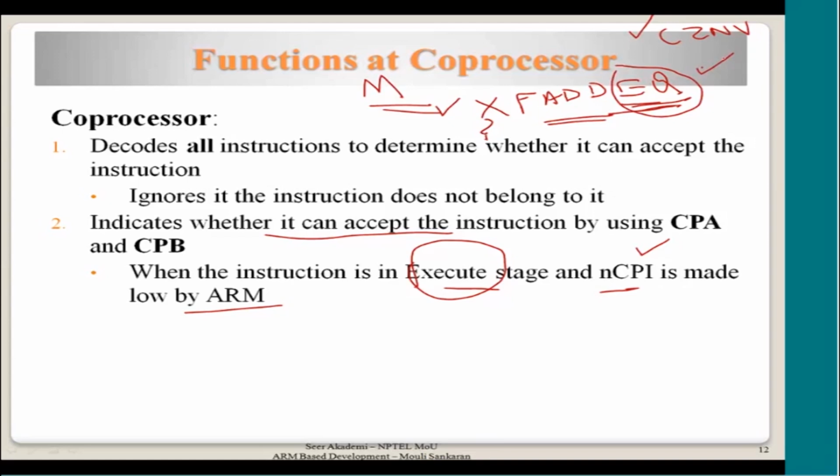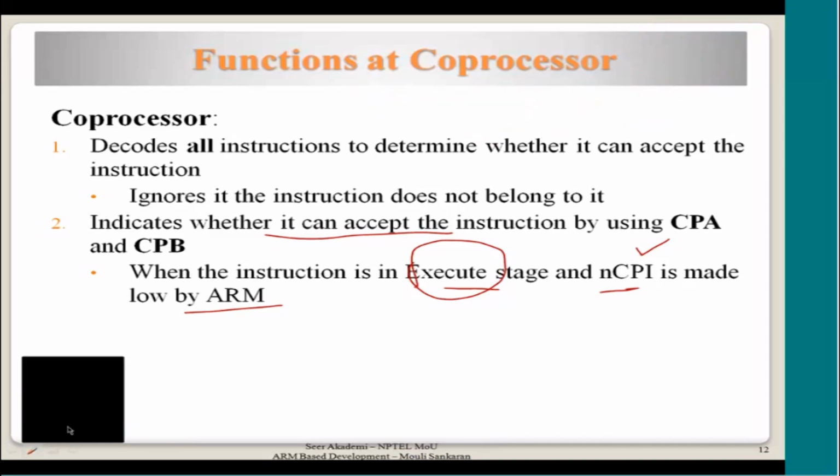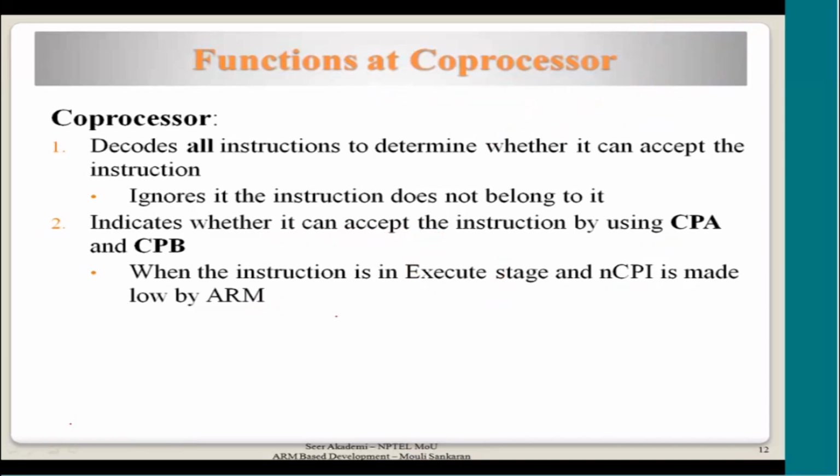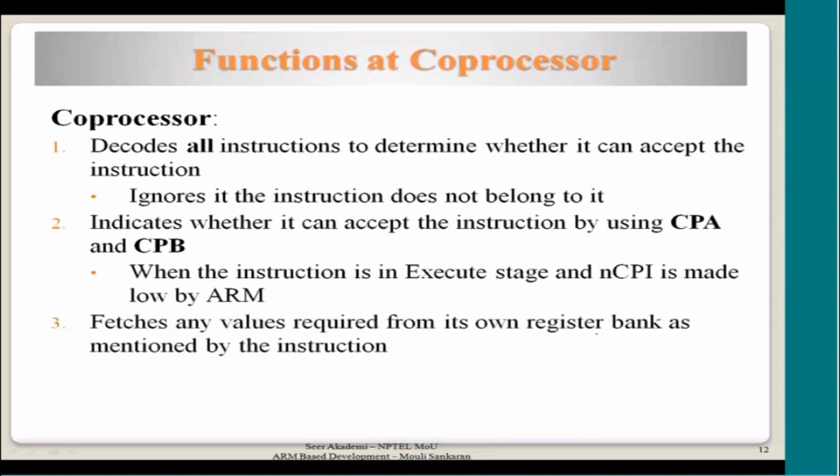So it can decide only based on its own flags. It cannot take a decision based on the flags in another coprocessor. So the conditions all have to do with the CZNV flags of the ARM processor. That is the only possible design in this scenario, because one unit has to decide the control flow of the whole program, and that is the ARM core.